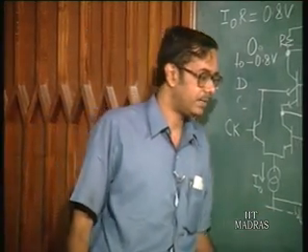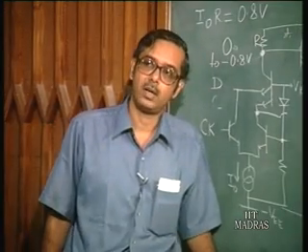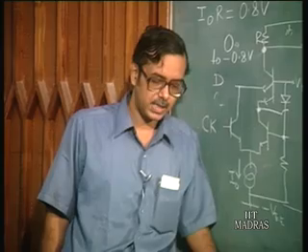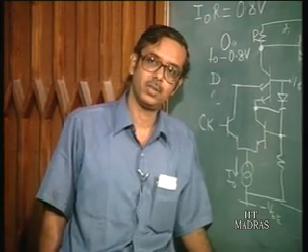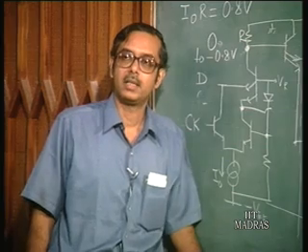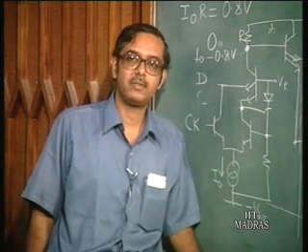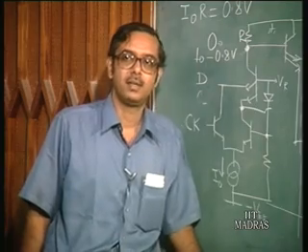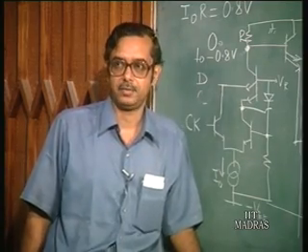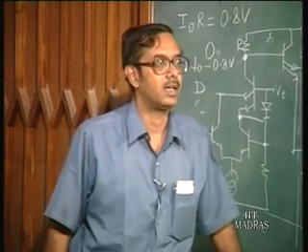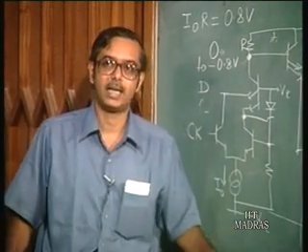Then there has also been a lot of work going on even further, because the problem is the ECL gate is a very high speed circuit. It in fact offers the highest speed, but it is still difficult to make large scale integration, because it is still very much power intensive. There is a lot of power dissipation, and so you cannot make very large, very highly dense circuits.